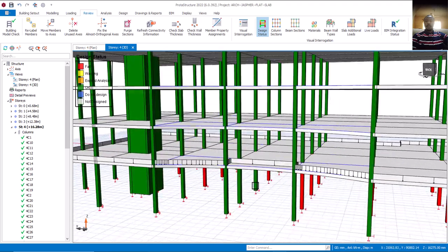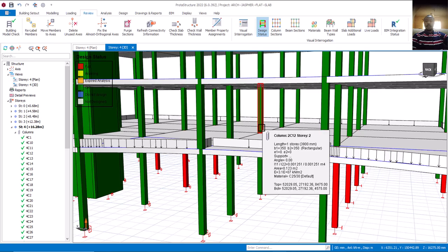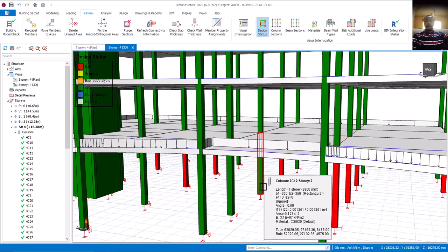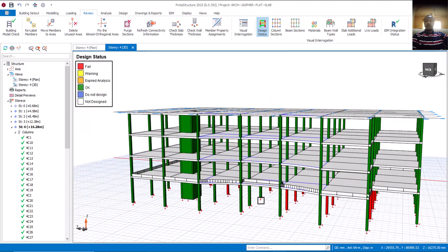Or you leave it like this. At the base, the first floor is 400, while from the second floor to the last one is 350 by 350. Once you have detailed one, automatically it represents others, whereby during your detailing you make it known where those columns are being located. Is that okay? All right, that is fine.